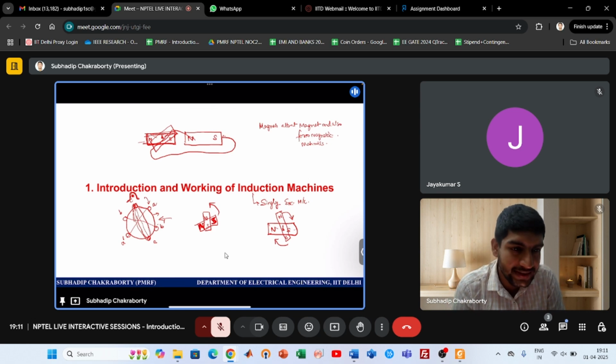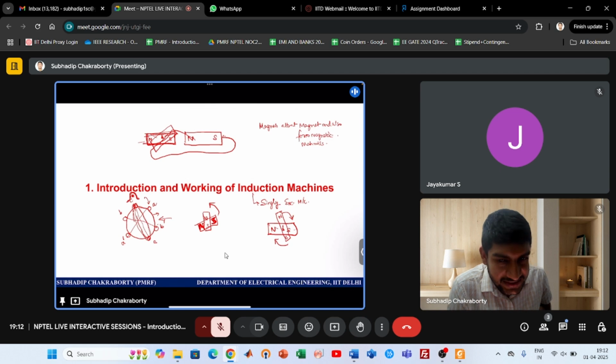Stator is a slotted structure where you place conductors of all the phases, right? So conductors are connected accordingly. For each phase, you have a dedicated series of slots where you place the distributed conductors, and accordingly you tap the windings out. That is how you construct the stator windings for these kinds of machines, which rotate on the principle of rotating magnetic field. We will discuss how.